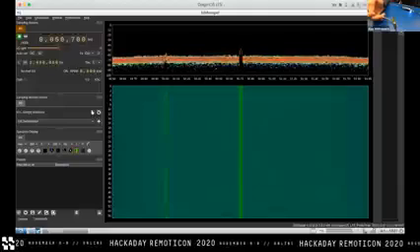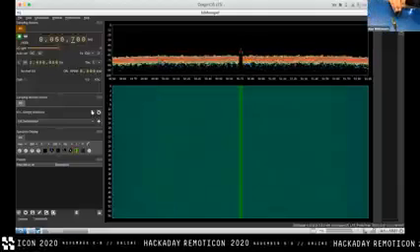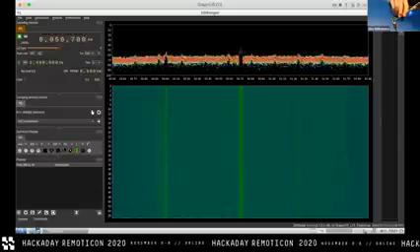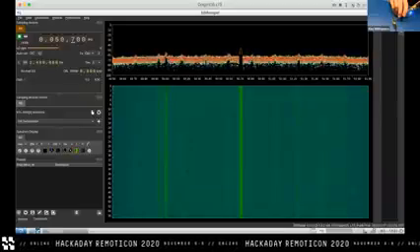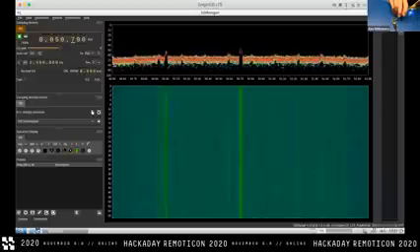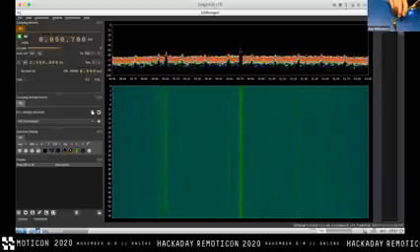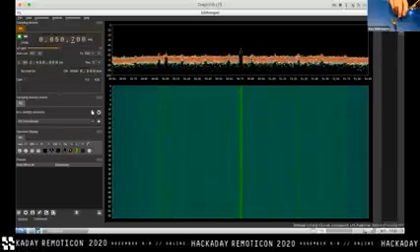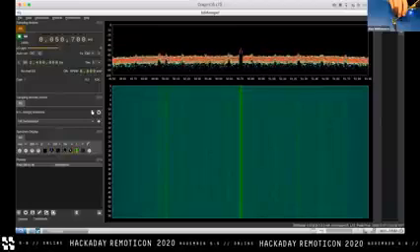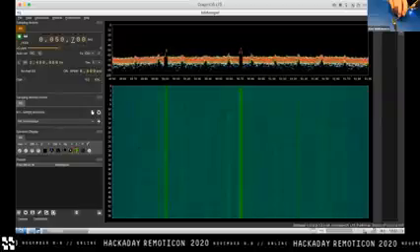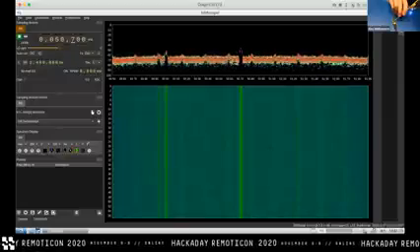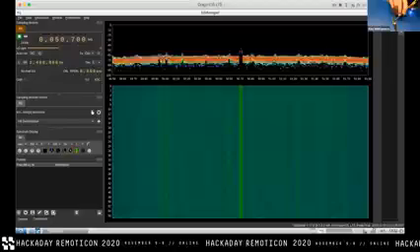And over here, we see the signal a bit, but then let's do that IO pin trick where I put the probe basically like a projected shadow of the trace that it's on. If I move around, ooh, I start to see a lot of stuff going on. But there is a pin somewhere on this side of the board. This is where having the buzzer, actually, I don't know that it's worth the cost, but it's certainly nice. There's a pin somewhere right over here, right about there, maybe? Something like that. That looks a little bit like something going on over here is probably what we're after.